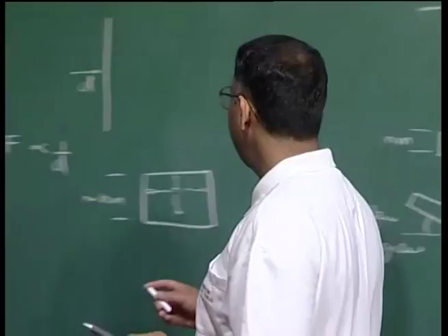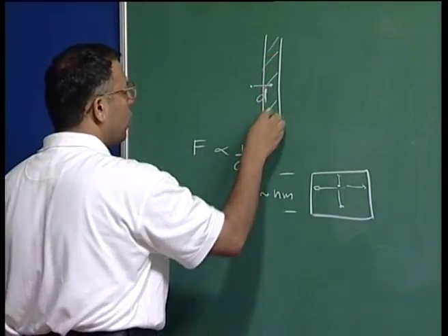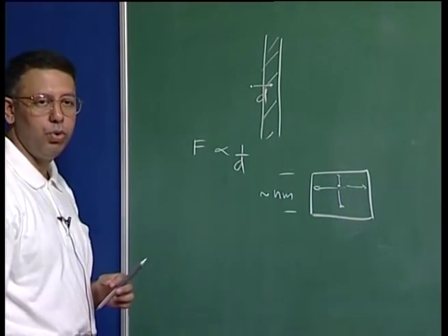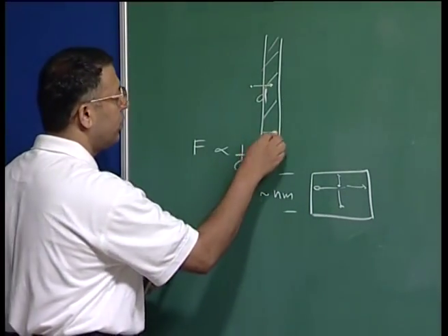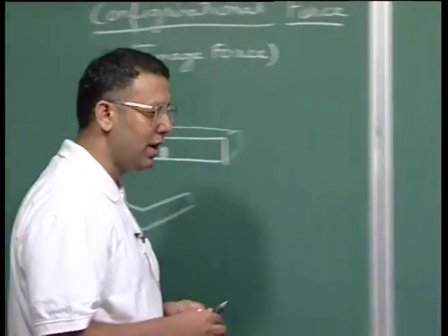So, if you had a free surface like this, then there will be a region very close to the free surface wherein my image stresses will be so large that it can support no dislocations, and all dislocations in the region would come and sit on the surface. Given, of course, that these dislocations are glissile, and also the fact that they face an image force greater than the Peierls stress, and assuming that the Peierls stress is not too large.